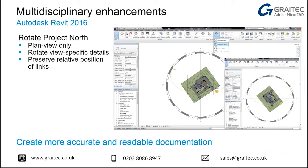We've got some improvements to Project North. Now, Revit has three separate coordinate systems. It's got the internal one, which you don't need to worry about. It's got a project, and then it's got a shared. The project coordinate system and our True North and Project North allow us to have our buildings set up for solar study. We can rotate Project North in plan view.